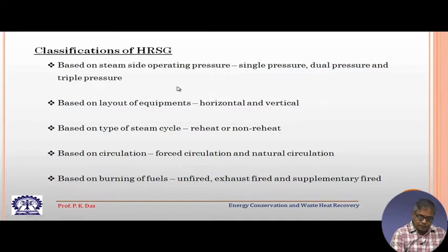That means there are two fluids in an HRSG. There is a gas which is passing over the surfaces, different kinds of heat transfer surfaces are there for an efficient exchange of thermal energy, and on the other side there is steam or steam water mixture.